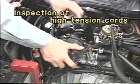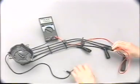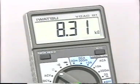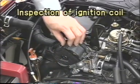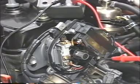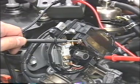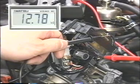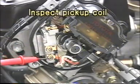Inspection of the high-tension cords. Measure the resistance of the high-tension cords with an ohm meter. Inspection of the ignition coil. Measure the resistance of the primary and secondary coils and check that the resistance is correct. Next, measure the resistance of the pickup coil.